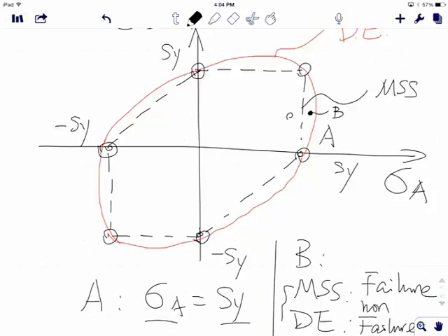Make sense? Here's a good example. If you drive on a Texas highway, as long as you don't exceed 80 miles per hour, you're fine, right? Speed limit is 80. If you drive to New Mexico or Arizona, then the highway limit is 75. That tells you if you drive 80, you're already speeding. So distortion energy is a Texas highway. Maximum shear stress is a New Mexico highway. Get it? If you drive 80, you're fine in Texas, but you're not fine in New Mexico. Get it?